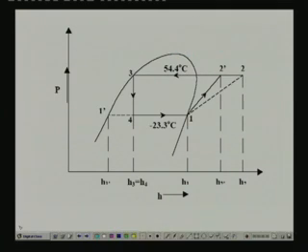Okay. So, this is the information that we have. From this information, how do you find the state properties, various enthalpies, temperatures at various points? Let us begin with the saturation line, that means point 1 and point 3. This point is already fixed because we know the temperatures, and we also mentioned that this is a saturated condition. So, on the saturated line, specifying any one parameter is enough.